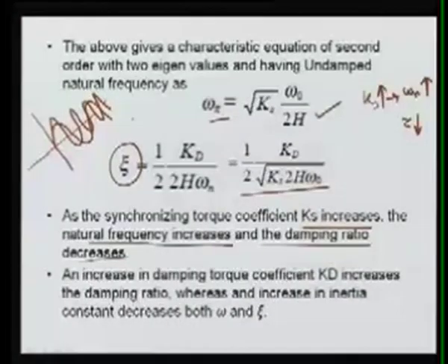For example, let's suppose the system decays in 2 cycles, here it's 1.5 cycles. So if you are increasing this K, what will happen now? There will be several oscillations, and also the damping will go on for a longer period. Means the damping coefficient is reduced, so it will take longer time to damp out.